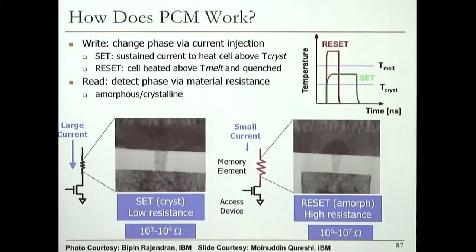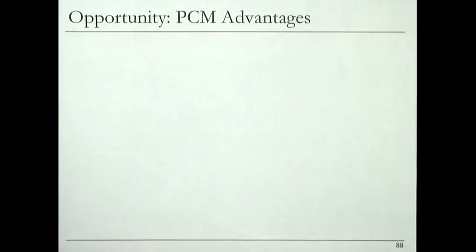So you can actually see these things, which is interesting. But there's a huge difference in the resistance, as you can see. That enables the access device to operate fast. If the resistance levels were really close, then it would be difficult. In DRAM, it's actually very close. That's the problem, actually, the charge levels. Whereas here, there's a huge distance between the two states' resistances.